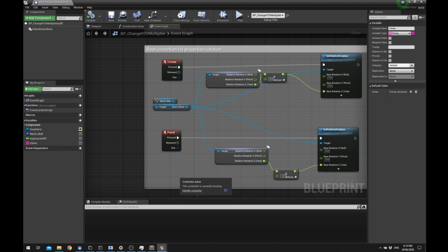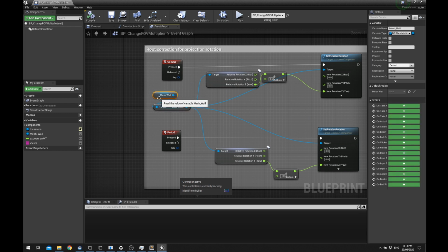What I have done as well, so this is where I've done something tricky and there are other ways to do it. Sometimes, because you're using a VR headset to create an alignment of your world, effectively with nDisplay we're trying to say we have an accurate representation of where the origin of the world is and which way it faces. And we're using a very blunt instrument, which is a VR headset, pointing it in a direction and just saying, you're there. And that actually might be out. No matter what you do, it's going to be really hard to calibrate that correctly. So where you were facing the headset, that's going to be your X forward direction.